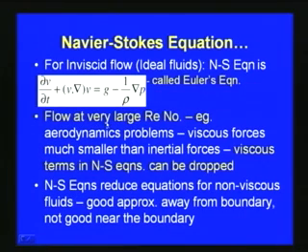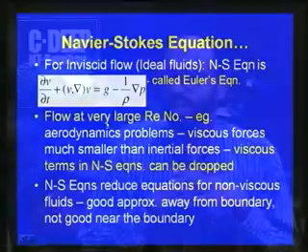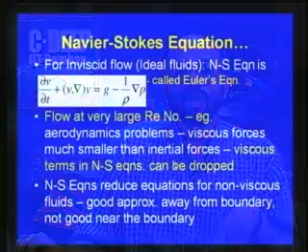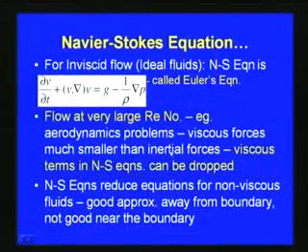Also, for flow at very large Reynolds number, for example in aerodynamics problems, viscous forces are much smaller than the inertial forces, and the viscous terms in the Navier-Stokes equation can be dropped. So, for high Reynolds number flow we can drop the viscous terms, since the viscous forces are much smaller than the inertial forces. And the Navier-Stokes equations reduce to the equations for a non-viscous fluid.